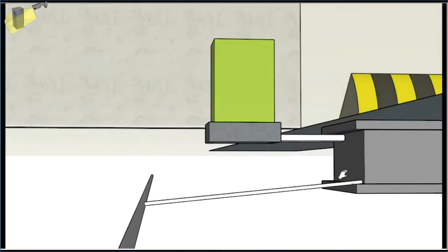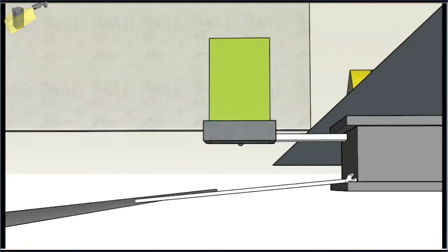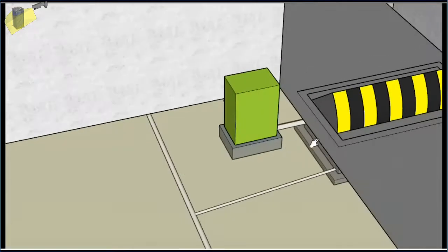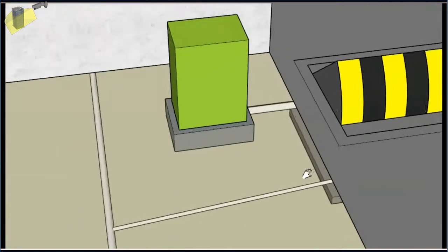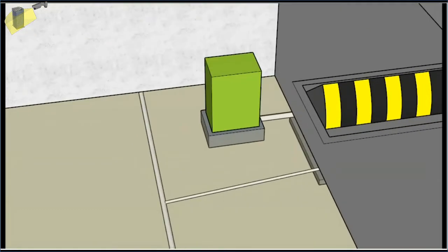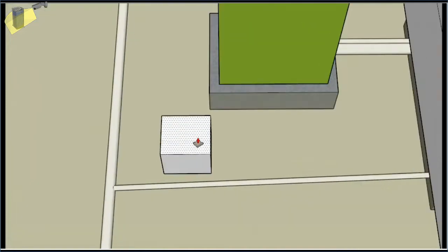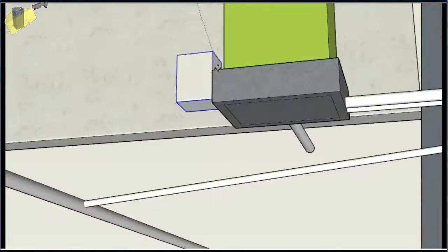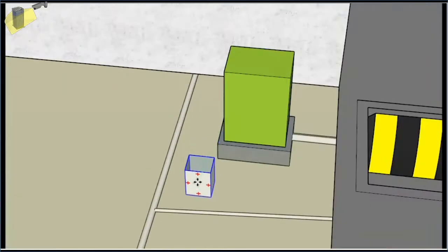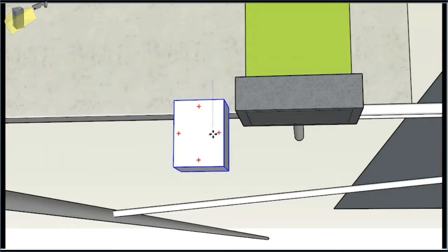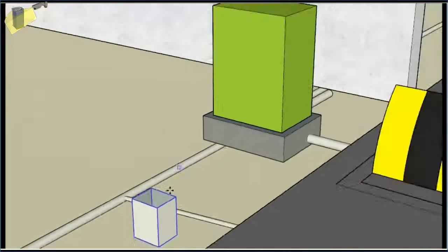A drain pipe can be connected to the sewerage. It should be slanting so that the water goes down. But if there is no sewerage, if there's a green belt, what we can do is make a pit here, inside the grass or whatever the green belt is, and have a submersible pump inside the pit.